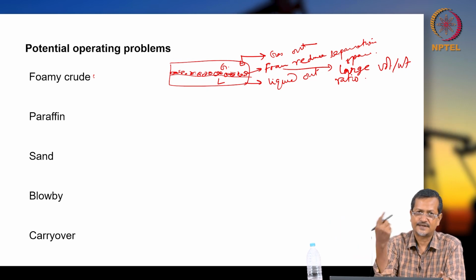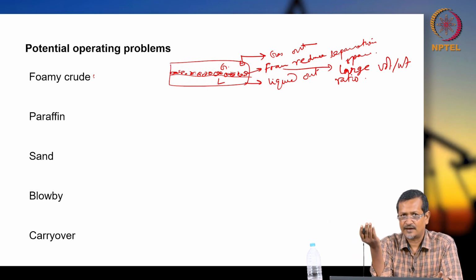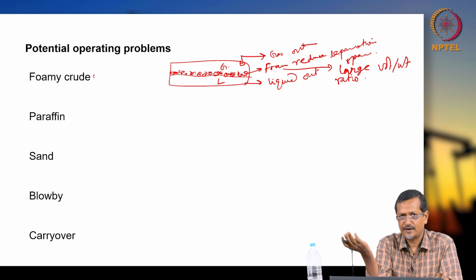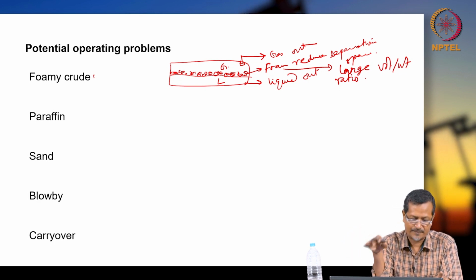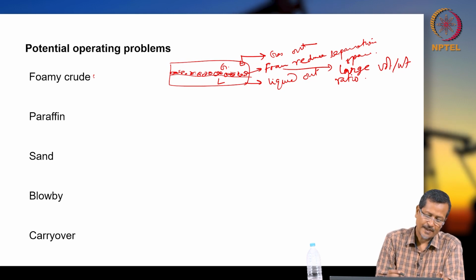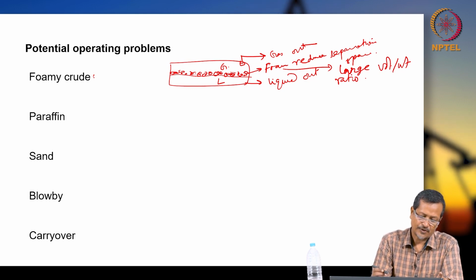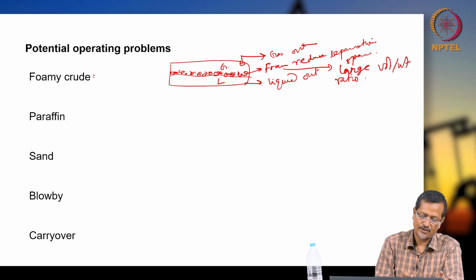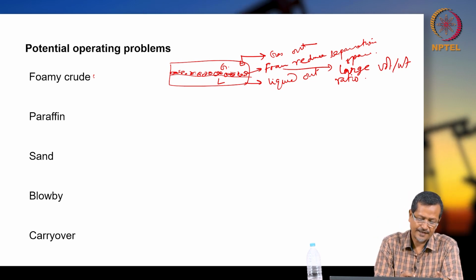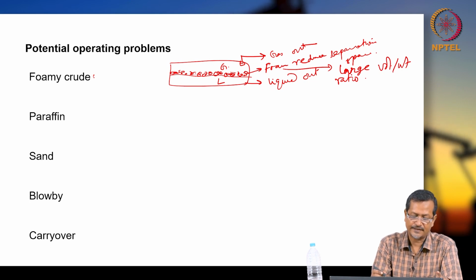So when it creates a wrong signal, the liquid out valve can be opened before the required time or after the required time. With an uncontrolled foam bank, it is impossible to remove separated gas or degassed oil from the vessel without entraining some of the foamy material in either the liquid or gas line.